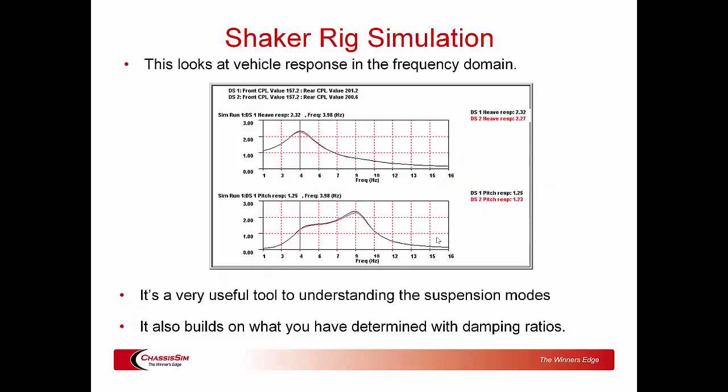Okie dokie. So once we've got our damping ratio, once we've calculated our lateral load transfer distribution, once we've determined the tyre model, and once we've done our springs and our damping rates, this is where our simulation tools come into play. And our first port of call is the shaker rig simulation.